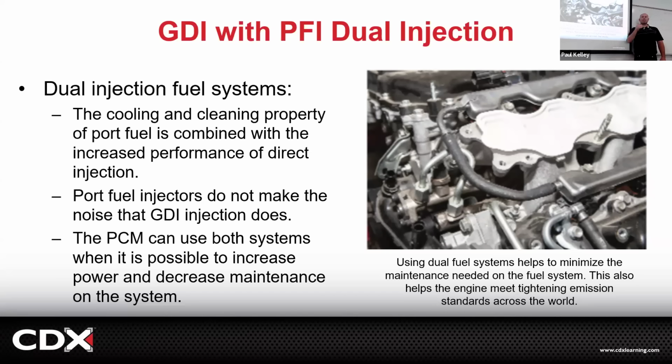And it had that fuel imbalance too. Changed it over to direct fuel injection only, misfires right there, bumbling, stumbling, running all sorts of crappy, set the misfire code, set the fuel cylinder imbalance code, and it was like, well, a bunch of lights, Christmas tree lit up. So what's the problem? Ran good with only port, ran bad with only direct.